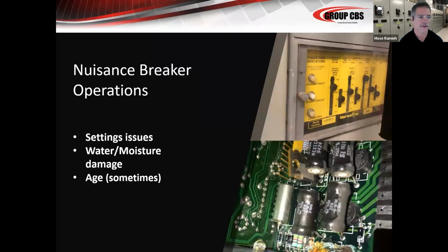Another one that we talk about is just aging trip units and moisture. And I'm going to mention moisture again on this particular slide. Once again, aging trip units more than likely are going to cause you nuisance tripping, right? Sometimes they just don't operate at all. And that's, once again, why we periodically need to test our trip units. We periodically need to inject them either with secondary current or primary current so that we can continue to make sure they operate.